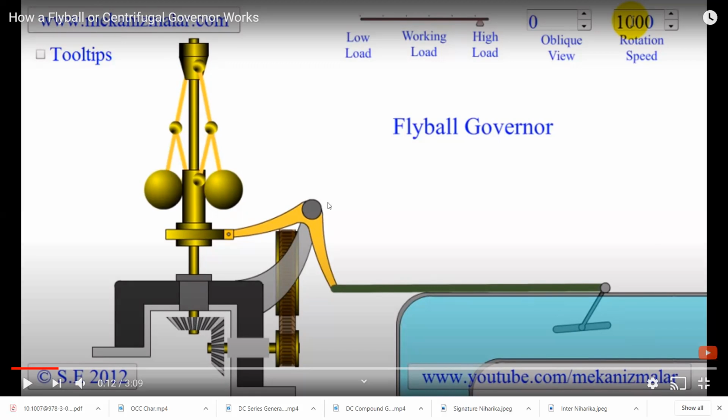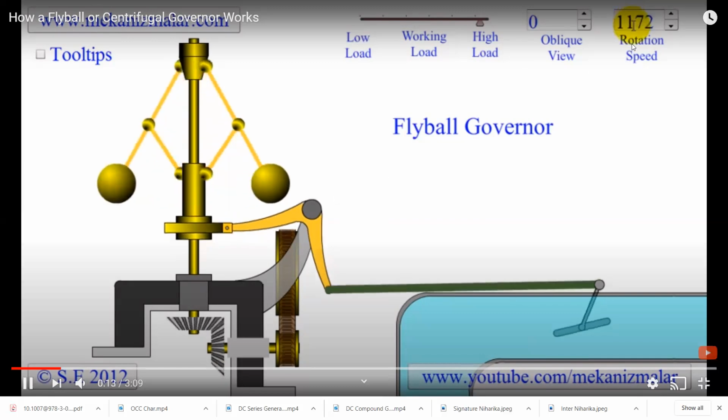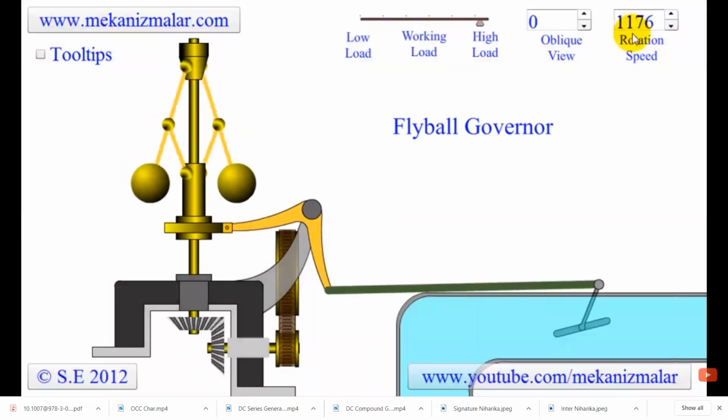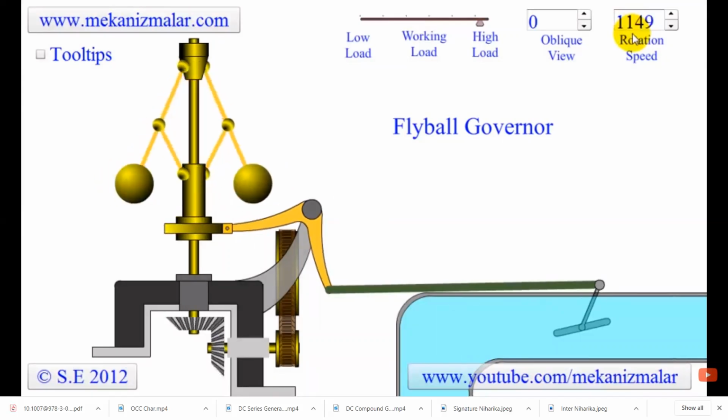Now we'll see how it behaves whenever the demand is decreased. And see here, whenever the demand is increased, previously that was 2000 rpm, or you can say anything. Now as the incremental of demand takes place, the speed is decreased, right? And with respect to incremental steam, the speed is adjusted to increment the value. Like that it will be adjusted till we reach the rated value, that is the optimal speed, that is 2000 here.